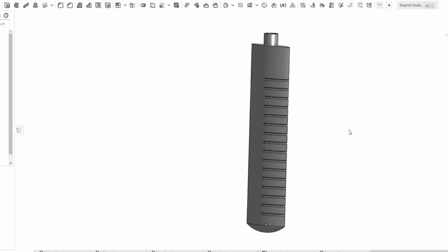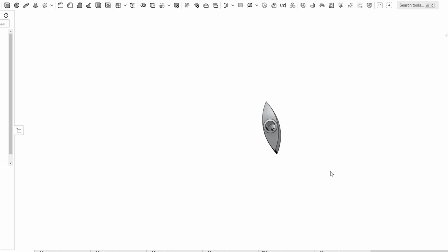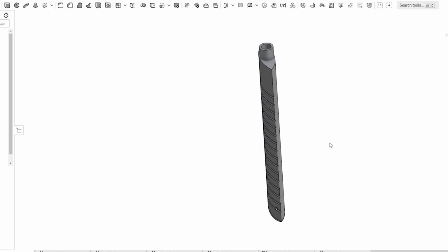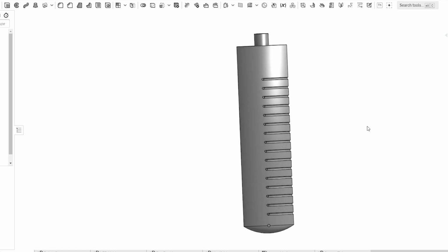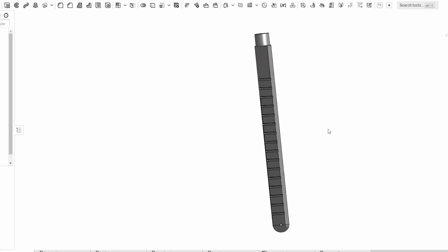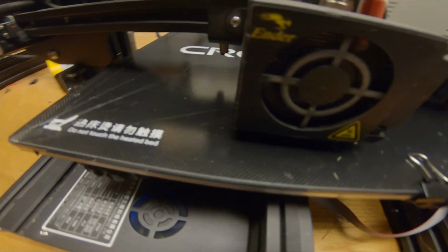The idea of the first rake design was to design a streamlined shape with holes along one side. I figured this would be an area of the rake with lowest pressure and would help pull the smoke into the stream. So I printed this up and set to fitting it into the wind tunnel.